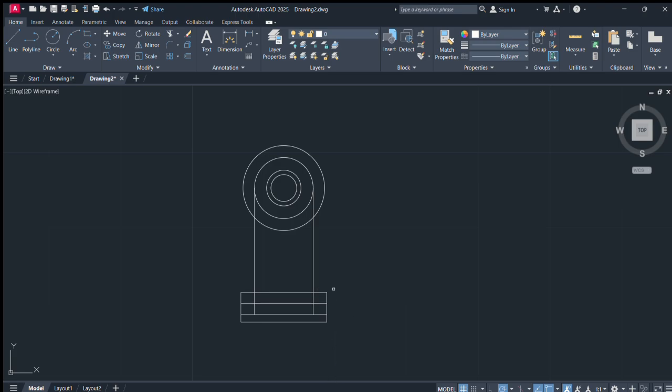Alright, so we need to make the arcs that are between the line that we have and the protrusions that we have from the top. For that, you're going to go to the fillet tool and enter a fillet radius of 1.6. Then click the top line and the line that is protruding, just like I showed you earlier. Since I don't have this line, let me just bring it back.